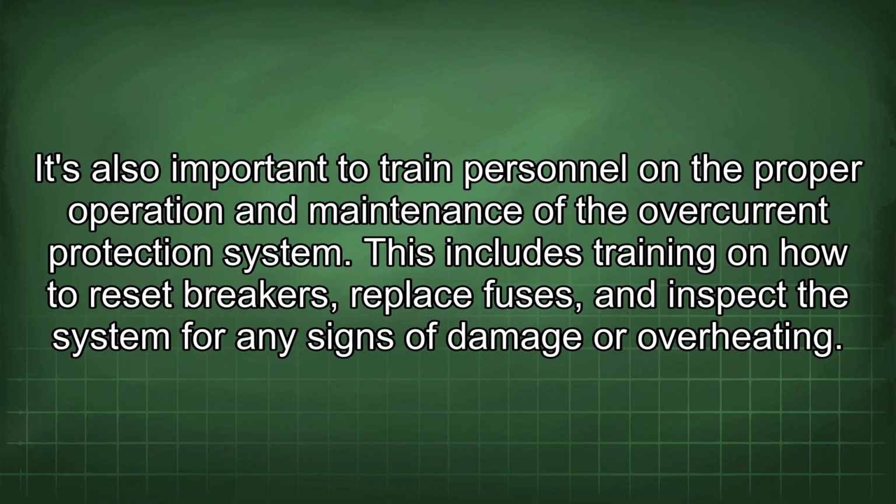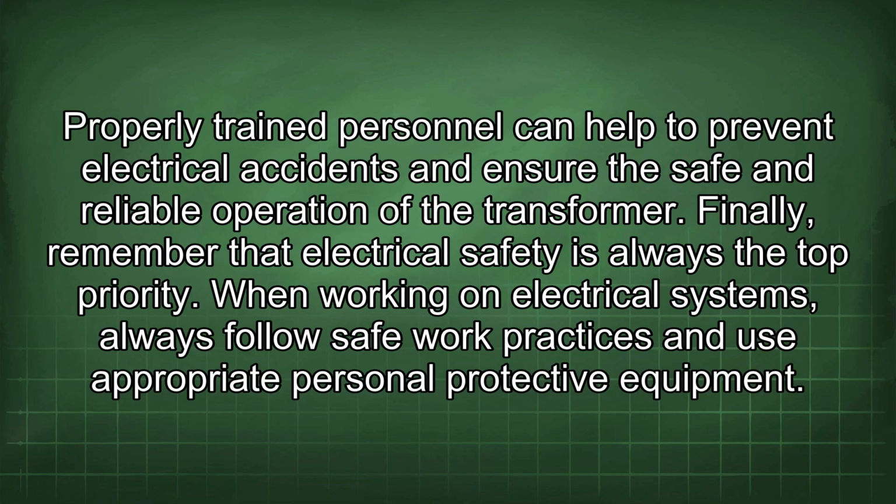It's also important to train personnel on the proper operation and maintenance of the overcurrent protection system. This includes training on how to reset breakers, replace fuses, and inspect the system for any signs of damage or overheating. Properly trained personnel can help to prevent electrical accidents and ensure the safe and reliable operation of the transformer.